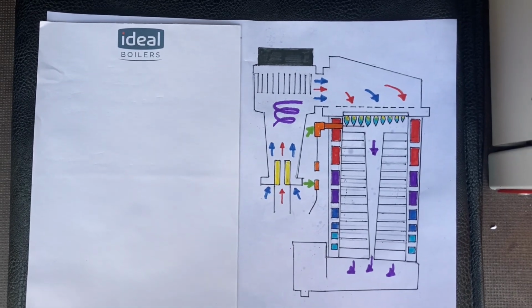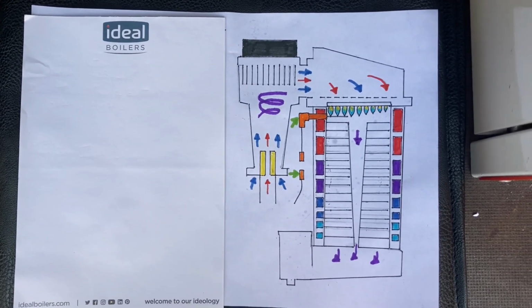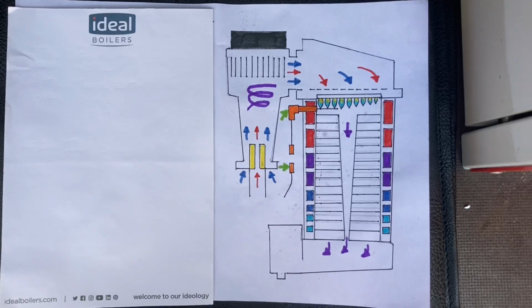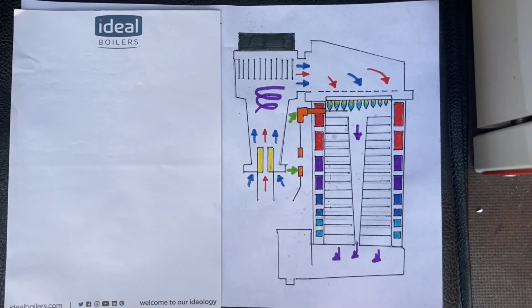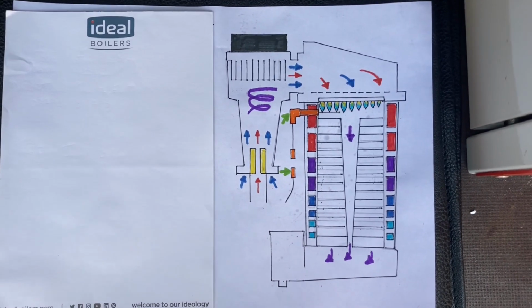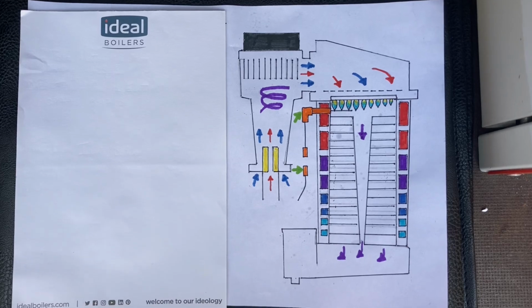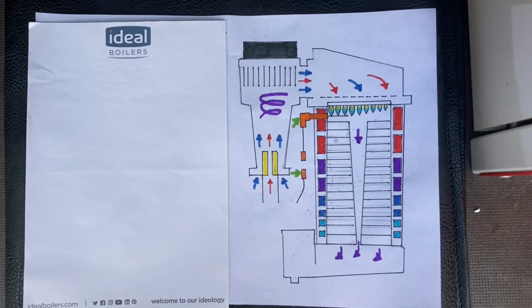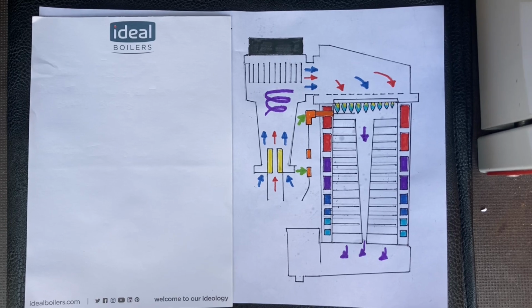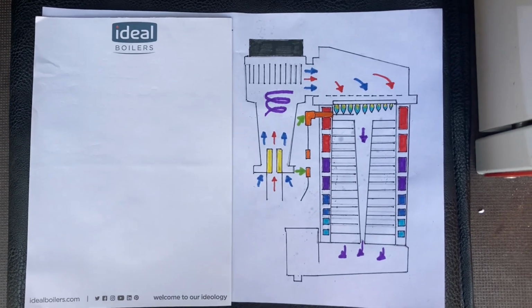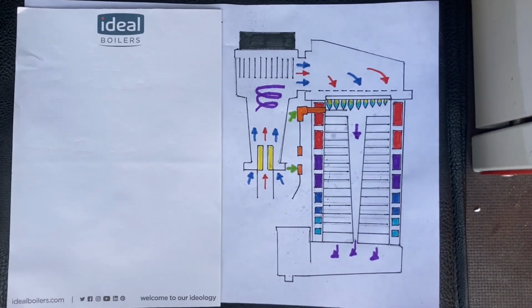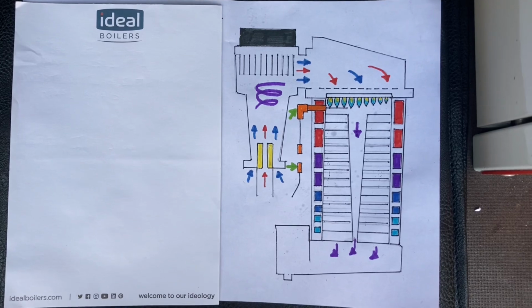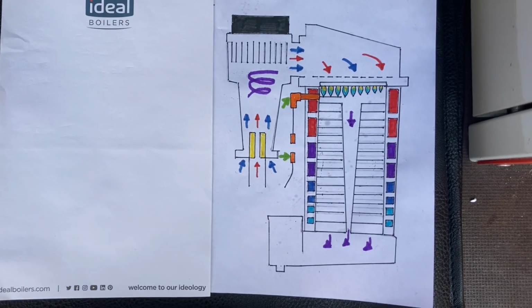Then I thought to myself, the only thing I haven't checked is burner pressure. If I go back to a standard efficiency boiler, I've done everything: working pressure, the thermistors, the harnesses, the circuit board, the heat exchanger, the plate heat exchanger. I had temperature clamps on everything. And I thought, on an atmospheric standard efficiency boiler, I could check the burner pressure, and I can't on this.